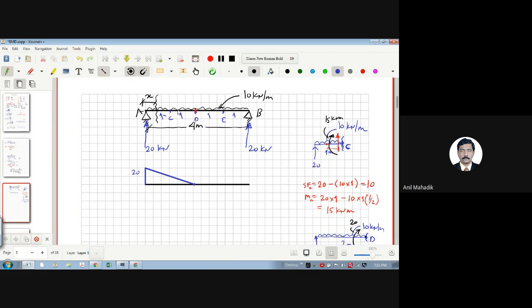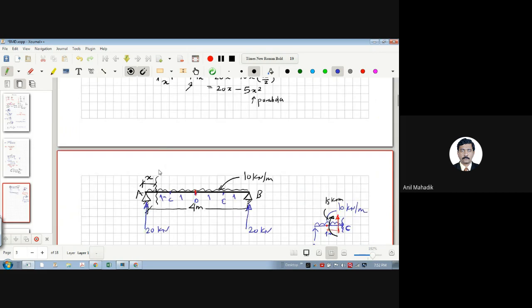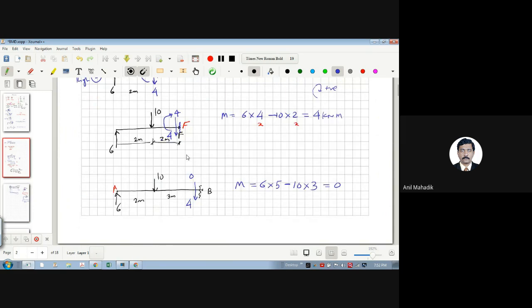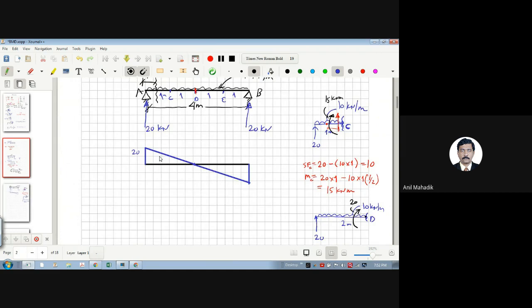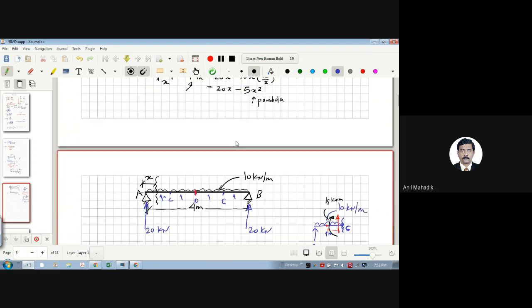And the same procedure, start from the left side. As you go ahead, you will see that your diagram is going to be ready like this. And this value is also going to be BC, because the right side is 20. So you can follow the same procedure I explained earlier. By judgment, later you will get an idea of how these look. So this value is positive, this is your negative value due to the sign convention of shear force SFD. So this is your SFD. This value is also 20 and it is linear because of that function mx. Yes, mx is coming here as 10x.